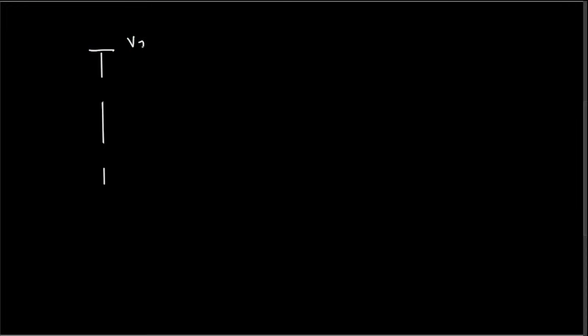Voltage source is VDD, the first resistance is R1, the second resistance is R2, and the voltage in between is the gate voltage, and this one is connected to the ground. In the Thevenin circuit, when we find the VThevenin, we combine this Vg and the ground into one voltage. In order to do that, we have to see what's the voltage on this R2.